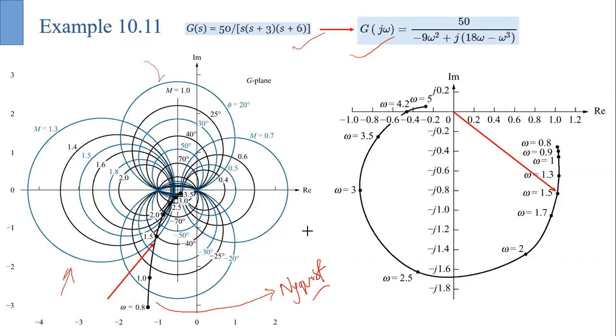There are two ways to now figure out the closed loop response. One way is the polar plot, which is shown here. Say we are willing to find out this intersection point. At this intersection point, the magnitude curve that is related is this one, which is 1.3.